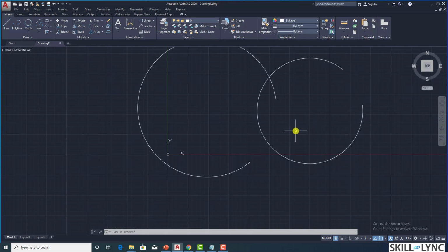This is your arc, and replicating the command again using center and the start point of arc like this, and then specifying the chord length, say 45. Oh sorry, this doesn't fit between the start and end point, so it shows invalid.